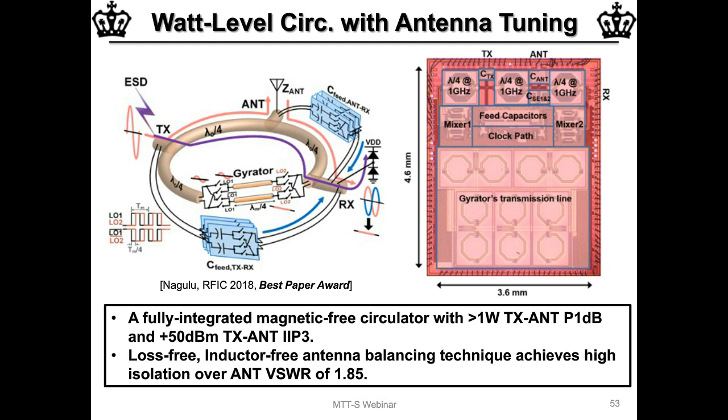then you have no spurious emissions. But if there are some small timing mismatches, then you will see some leakage of the clock signal to the antenna and some cross-modulation terms between the transmitter signal and the clock that appear at the antenna. So there are some spurs that you will see. These typically tend to be out of band spurs, and so they can be filtered with an additional filter following